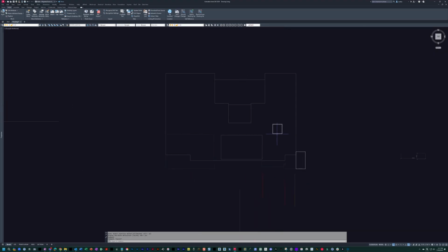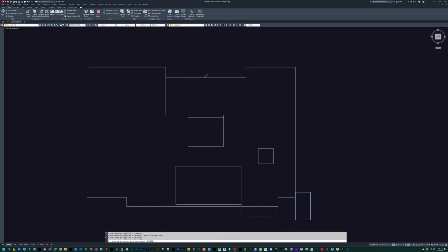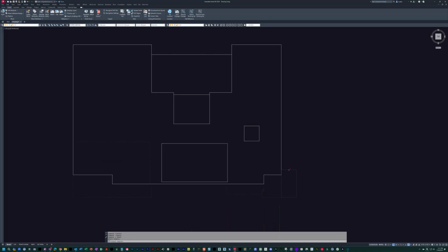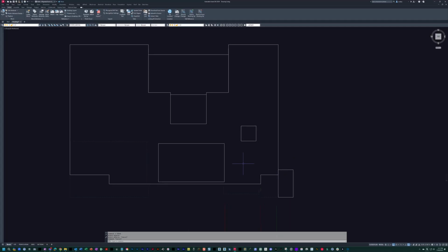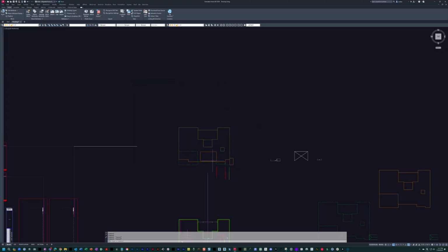so I'm going to reference edit and then grab all these things that we quickly just sketched. That should be everything we need. Add to working set, and I'm going to match properties because again, we've got to make sure that everything is set to by block, all that good sort of stuff. So now I'm actually not going to erase this just yet because there's one other thing I want to show. So now when I save, you see I have the outline of my building on the second floor.